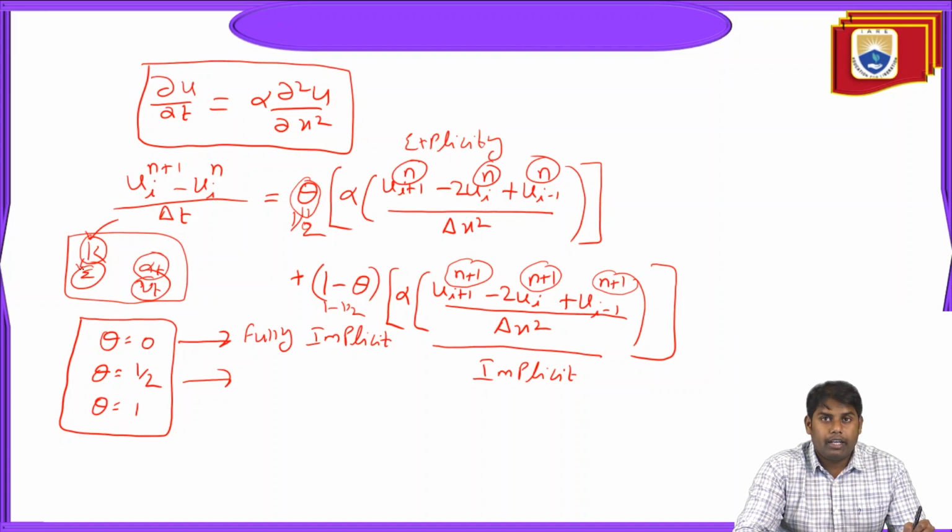So here, what is happening actually? When we are performing a simulation using turbulence models, let's say K epsilon, we need to know the initial values of these variables K, epsilon, alpha T, and nu T. If we are not able to guess it or calculate it, one initial step to find these values is to perform explicitly. Explicitly in the sense, initially you will guess the values. After guessing the values, you will get the values of K, alpha T, epsilon, and nu T. Once we get these values, we will check with the implicit scheme.